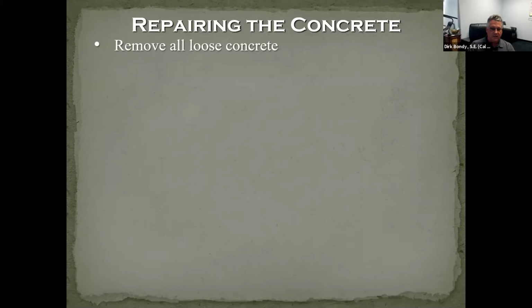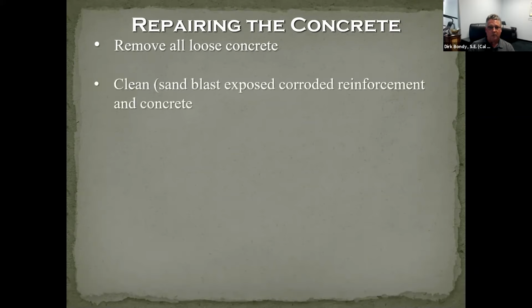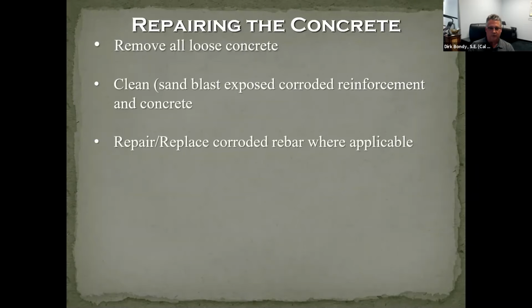So you've identified that you have a problem. Now what do you do? We start with repairing the concrete. We're removing all the loose concrete. We clean, we sandblast all the corroded reinforcement. You're trying to arrest the corrosion from continuing. Replace the rebar if you can, it's not that easy, but repair it, clean it.